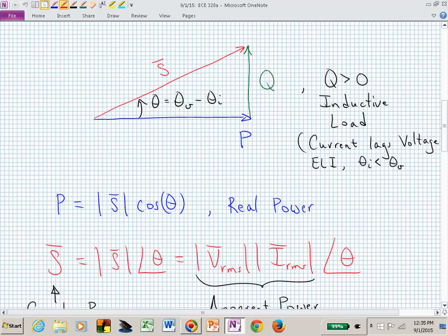If I gave you the hypotenuse, and then I maybe gave you the power factor. Here I haven't identified it yet, but the power factor is hiding there as the cosine of theta. If I give you the power factor, and if I tell you it's lagging or leading, that will tell you the angle value, because you can do an inverse cosine of the power factor, and if it's lagging, then you know that angle was positive. If it's leading, you know that angle was negative.